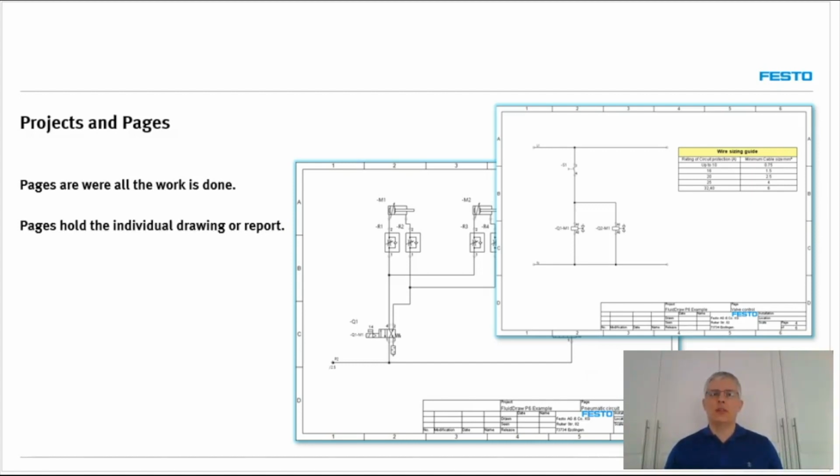The main thing to note is the attributes, including the title blocks and layouts and everything else that is associated with a page of drafting, can be pulled from the global settings, which are at the project level, or modified at a page level. Therefore, very simply, if you standardize on a sheet size, be it A4, A2, or A0 for your projects, but then for some reason one page needs to be changed to another standard, this can be modified at a page level. This gives a lot of flexibility to customers and allows them to work to what they need to do.